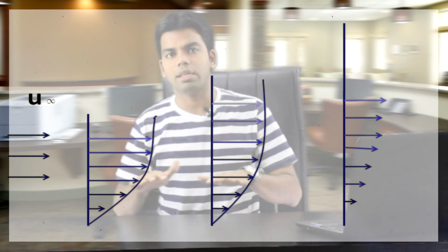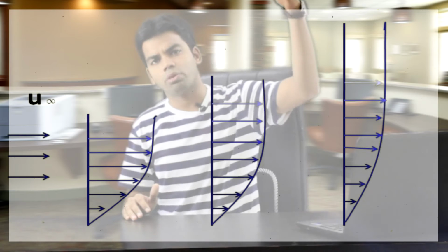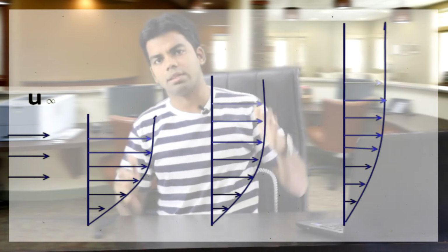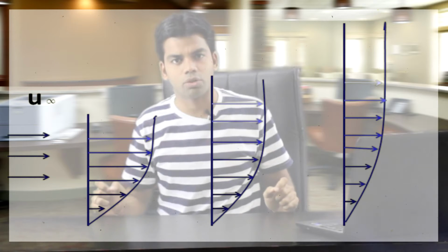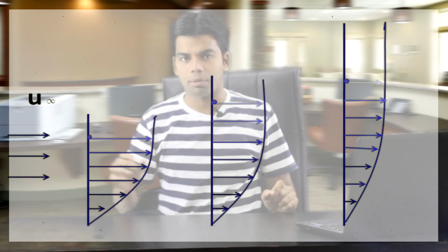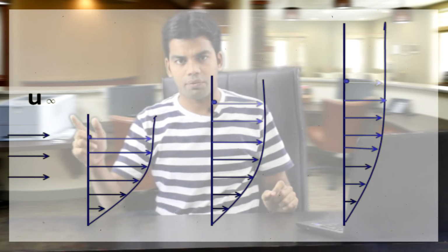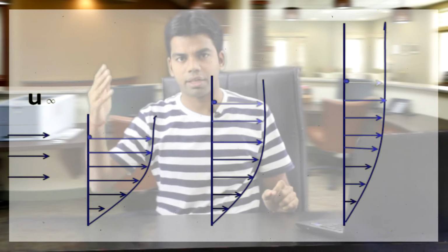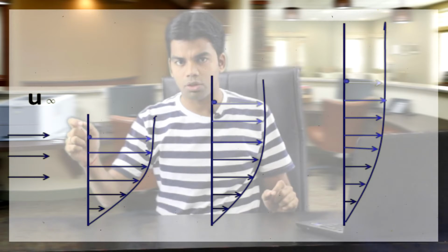but the velocity in the same layer will be less, and the velocity profile extends over a greater transverse distance as compared to the first and second points. Getting this thing or not? So if I join the locus of all the points up to which we get the velocity gradient, because after this point the velocity is constant and we get a straight curve, then up to this particular point we have the velocity gradient.